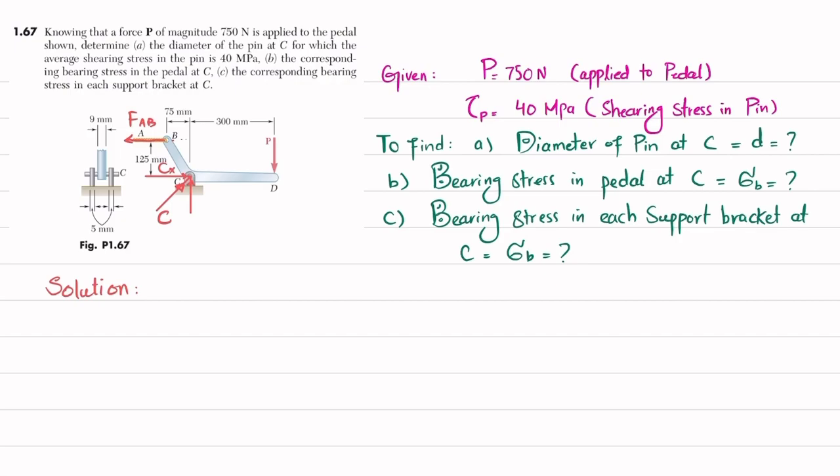This is the resultant. So how will you find this resultant? You can see that if I draw a dotted line, this distance is 125 and this distance is 300 millimeter and this height is 125. Clear? So by using the Pythagoras theorem, this distance, let this point be E, we will find CE. So CE will be equal to the square root of 125 square plus 300 square.